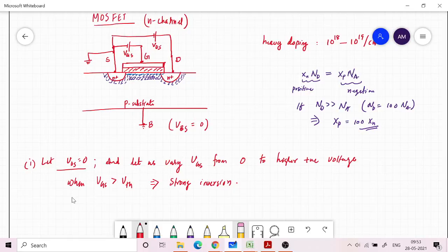If it is a conductor, then it will have some conductivity or resistivity. Now if you apply a non-zero VDS on top of this condition, then current can flow because there is a path for electrons to flow from source to drain.